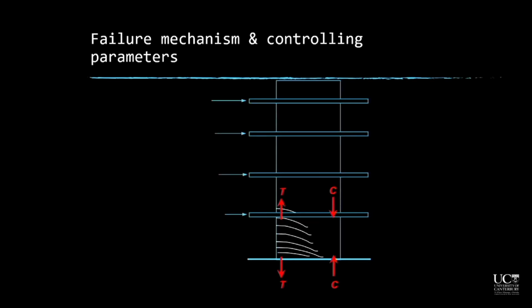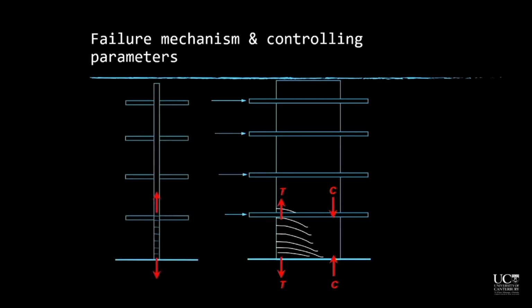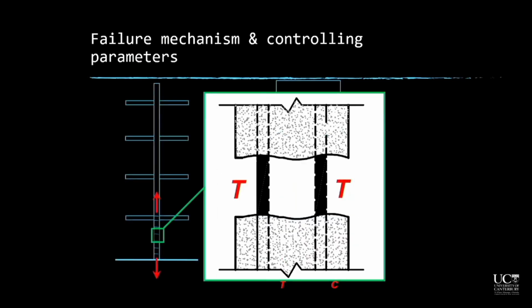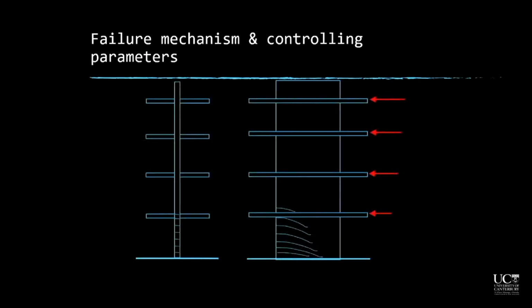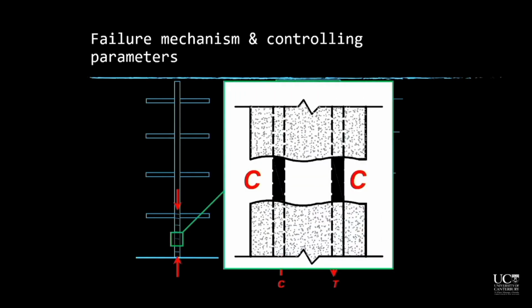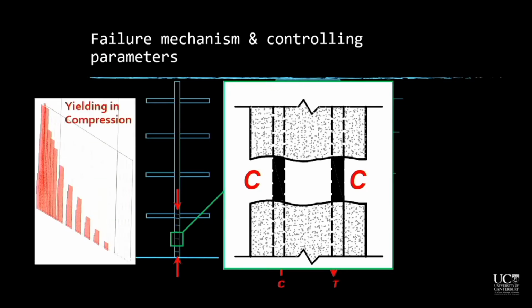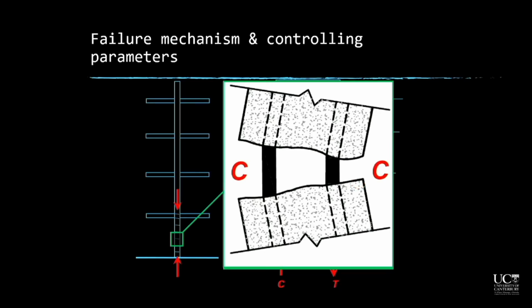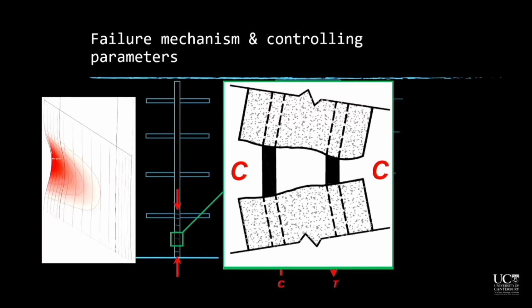When a structural wall is subjected to lateral loading at large in-plane curvature demands, cracks form in the tensile boundary regions, and then the bars are forced to yield in tension. When the loading is reversed, the cracks are still wide open. However, the tensile forces are now changed to compressive forces, and since the cracks are still wide open, the rebars are the only elements that are resisting axial forces. So these bars yield in compression, and when the compression occurs across sufficient length and height of the wall, the model defines the deformation pattern that requires less energy, which is the out-of-plane deformation.